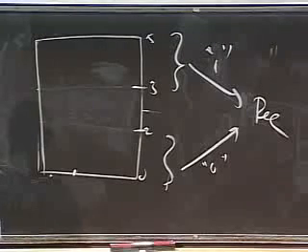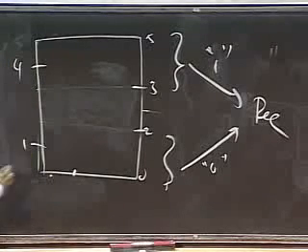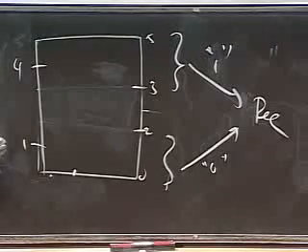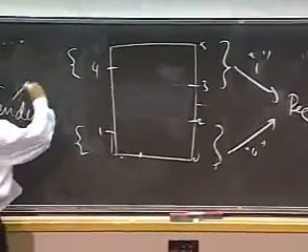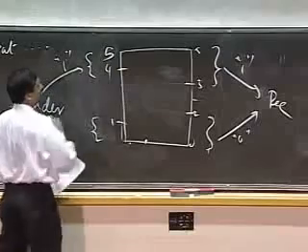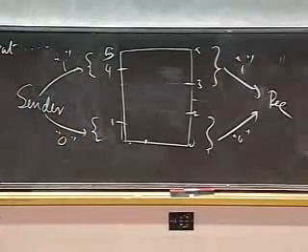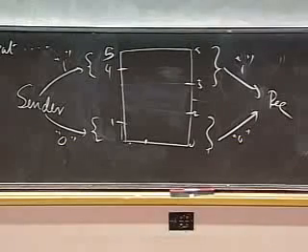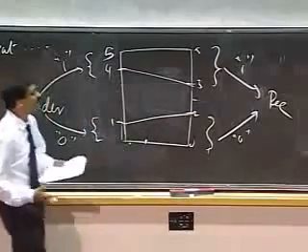So what I'm going to do is hold the sender to tougher standards, maybe 4 volts. That is, tell the sender that if you want to send a 0 or a 1, for a 1, you have to send a value between 4 and 5, and for a 0, a value between 0 and 1. So the sender is now held to tougher standards. Okay? So this is what my chart looks like.